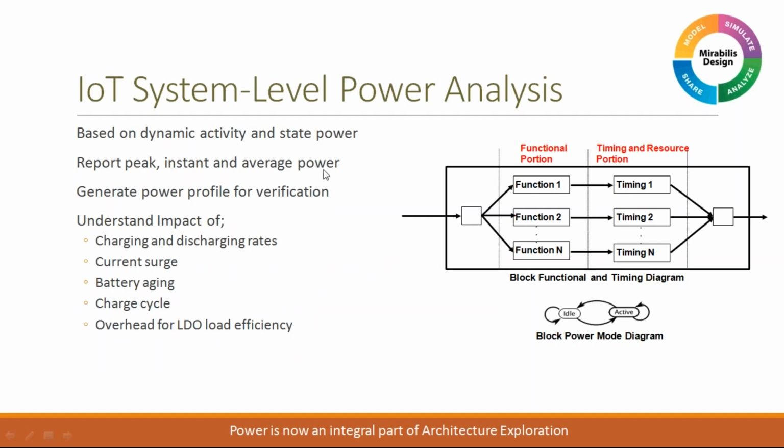To support that, as I mentioned earlier, all the libraries are embedded with both timing and power information, which means you have your functional execution in the block, and at the same time you have a timing execution as well. For example, when you're executing a particular function, that function takes a certain time period to be serviced on a processor core, or maybe on an arbitration scheme. That time impacts how much time that particular device is in active state, or in standby state or wait state.